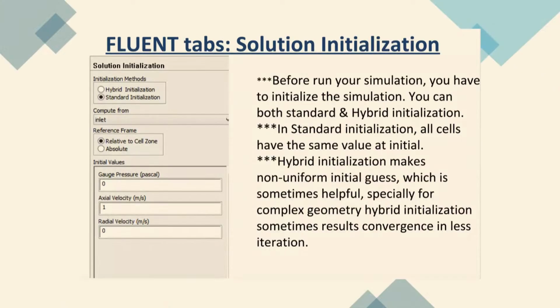Yeah, initialization. You have to give some initial value, and every time you run a simulation you have to do the initialization. There are two ways of doing the initialization. One is called the standard initialization, where you put in all the values, and the other is called the hybrid initialization. You don't need to do anything, just click it. It will do it all together, initialize your system and then start the simulation.